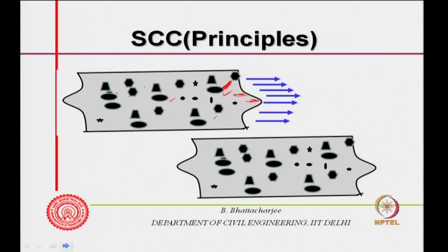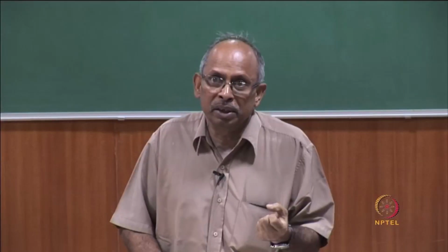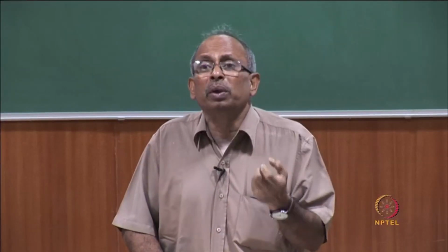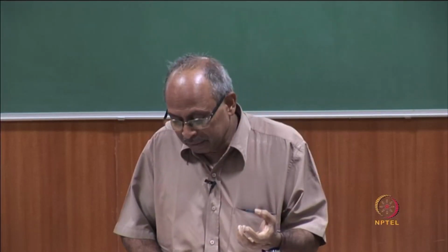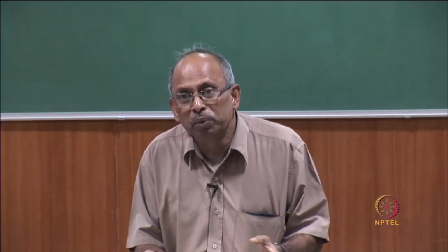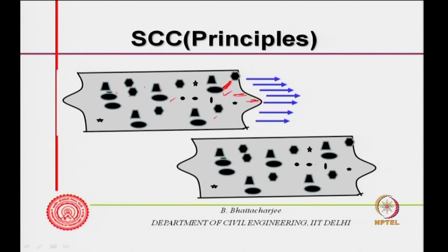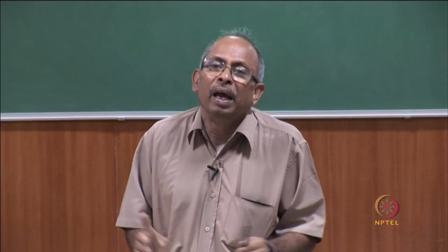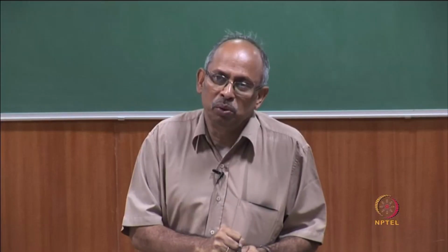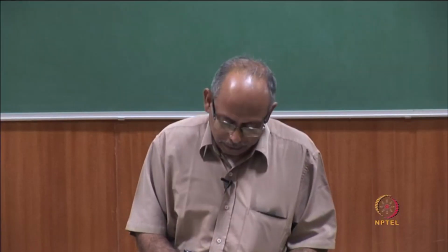Therefore, you must have less coarse aggregate content. Coarse aggregate content is less in this kind of system, all right. As it flows and moves out, the relative position remains the same, it does not change. So, after movement it should retain the same thing, it should retain its cohesiveness. Therefore, these are the two issues in self compacting concrete.